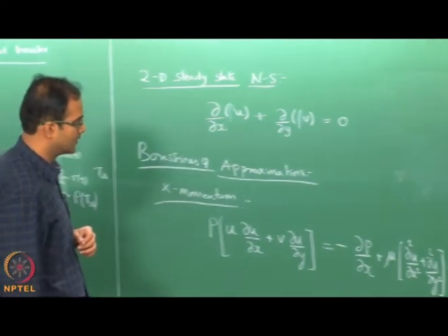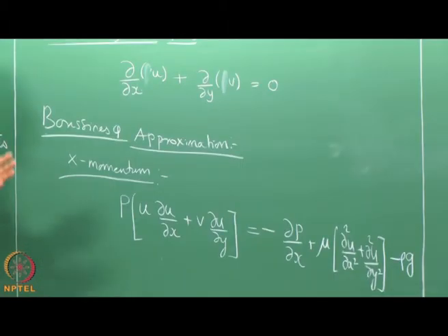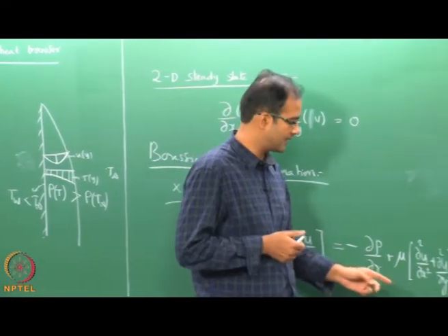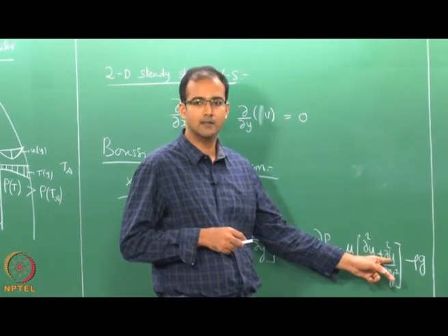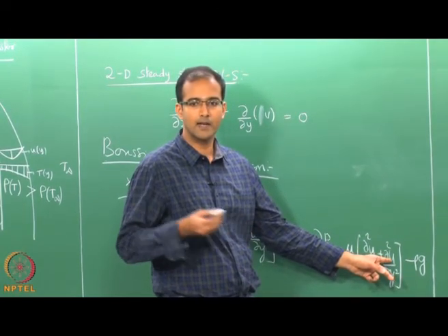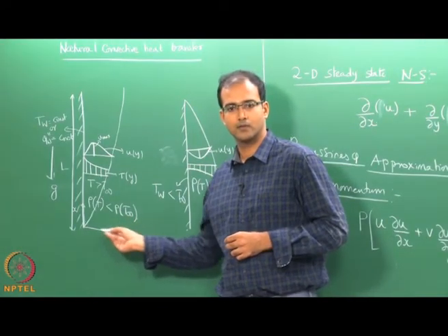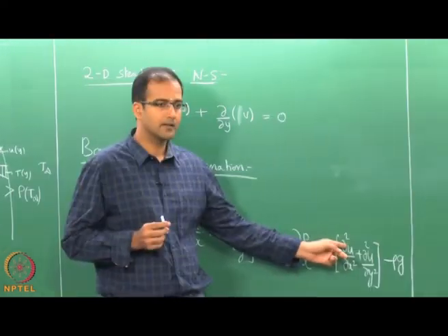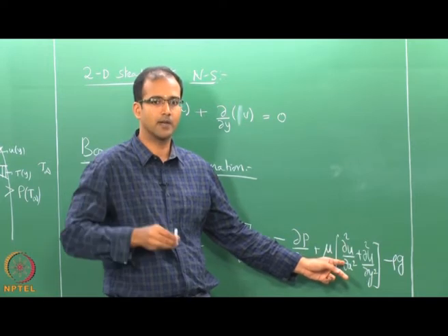Right. So, now once again, similar to the external forced convective boundary layer, if you do a scaling analysis, or an order of magnitude analysis, we can show that the diffusion in the y direction, here the y direction is the horizontal direction now, Cartesian x, Cartesian y, is much greater than your diffusion along the length of the plate.